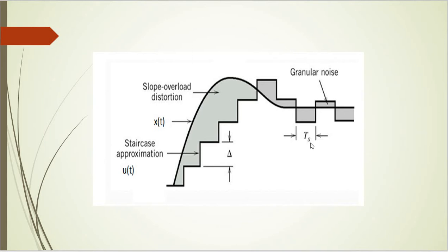And during this portion of the input waveform, we can see that the message remains a constant. The input is not varying continuously, but rather the input amplitude level is almost constant. In that case also, the stair-step approximated waveform has two levels, a plus delta level and a minus delta level, or the stair-step approximated waveform is fluctuating between two amplitude levels. And the error due to this kind of phenomenon is called granular noise.